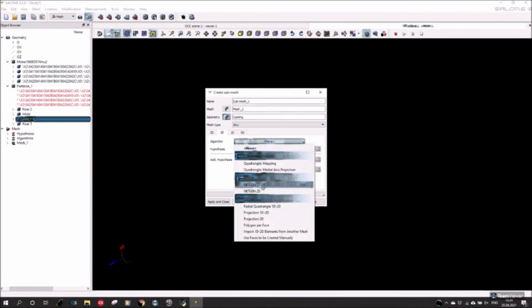It's not the end. I have risers, and I think that the mesh size in risers needs to be somewhere between the mesh size in the mold and the mesh size in the casting.